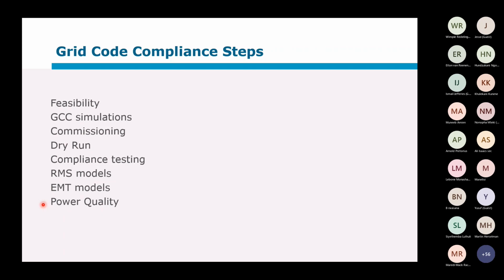And the timeline for that is typically a year or 18 months, because for power quality, to design and install a filter could actually take quite some time. The generator will have a temporary exemption during that period, provided that there's no significant negative impact on the network at that time. So, for instance, you're not causing major harmonics at a neighbor whose equipment will start to fail due to those harmonics.